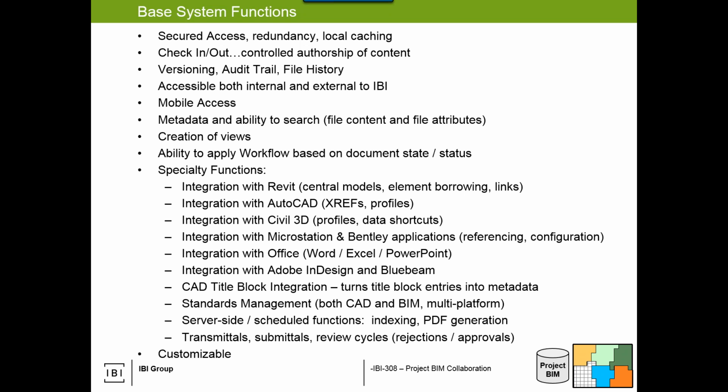Full integration with anything Bentley, and it integrates with Office, so you can push files from Word, Excel, PowerPoint, Outlook into ProjectWise, and you can also exchange metadata. So ProjectWise attributes can exchange with fields inside Word and Excel, for example. Title block integration, ProjectWise attributes can exchange and push to a title block in AutoCAD or MicroStation, not yet with Revit Sheets. And then the last one I'll touch, server-side PDF generation.